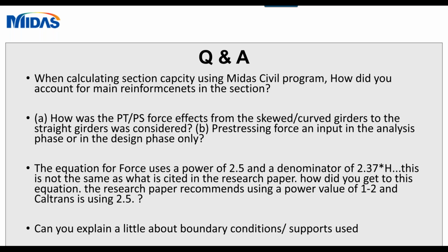Now both bridges work independently, and then also we played with different conditions connecting the columns to the superstructure. So I was playing using hinges, but there were some comments from the independent checker about how those hinges would work, if those are effective or not. So at the end, I decided just to have a rigid connection between the columns and the bridge. So everything is reflected in the analysis.